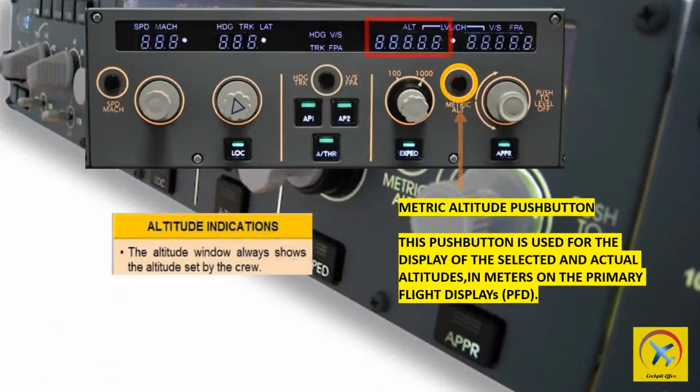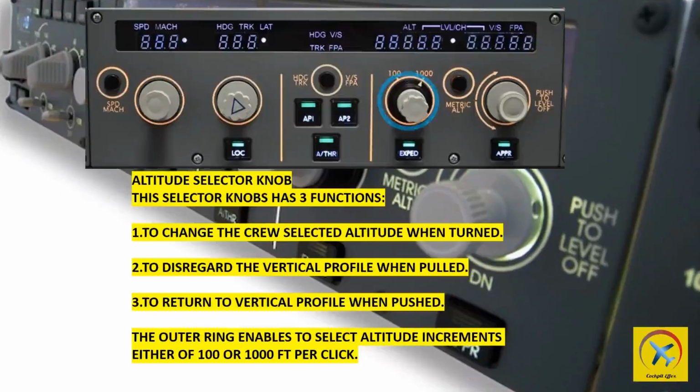The ALT window displays altitude selected with the altitude selector. The window never displays dashes, even when climb or descent is engaged. The metric altitude button displays the flight control unit altitude in meters on bottom of lower ECAM. The altitude selector changes the altitude displayed in the altitude window.